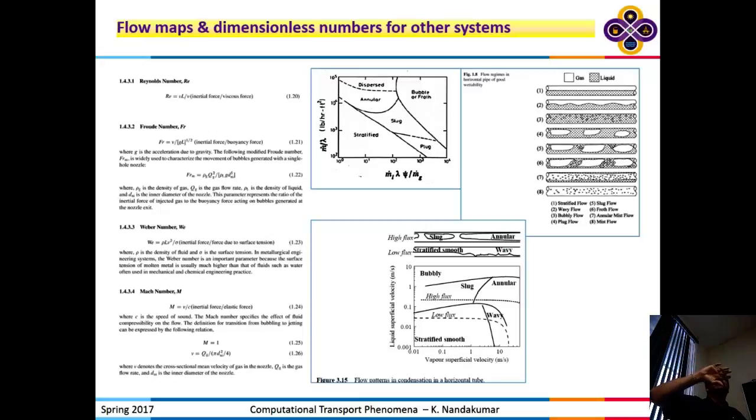Okay, even though you have kept the Reynolds number, there are other numbers that have to be kept the same, like Froude number. Froude number is inertia to gravity, and Weber number, it's viscous to surface tension forces. To keep the ratio of all these forces simultaneously the same as you scale up is a challenge. And petroleum engineers, I'm sure you face this whenever you build, for example, a scaled physical model of a reservoir, right? You know that you cannot scale everything about the reservoir down to that small laboratory scale. Okay, the reservoirs are spread on miles and miles, and your setup may be meters, right? And so you cannot preserve all these dimensionless ratios.